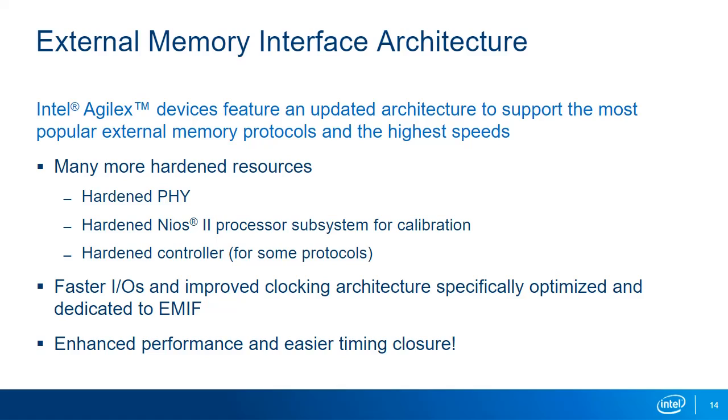Much of the PHY interface in the I/Os and in the read and write data paths was hardened, but the controller and the calibration sequencer were implemented in soft logic. In these newest devices, the entire interface for some memory protocols, except for the user logic that accesses the memory, is implemented in hardened device resources.